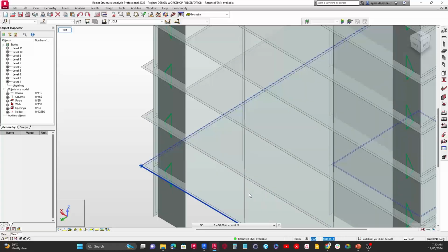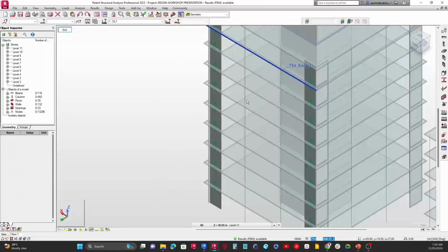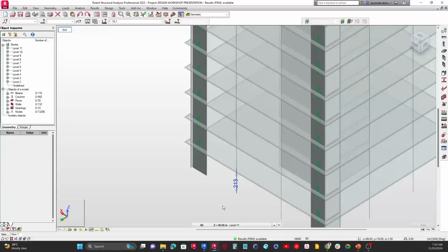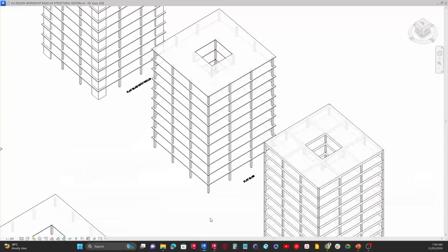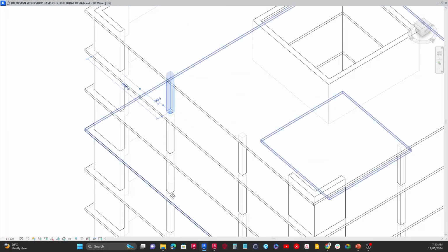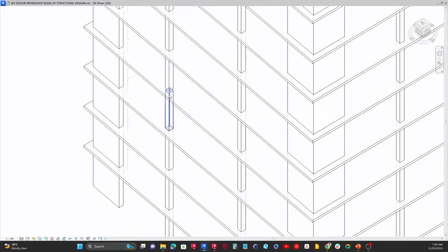All right, so the same thing applies to columns. The more loads that are coming from one floor to the other, it will lead to an increase in column section. So to practically demonstrate that, let me show you how it looks here. For instance, let's say this particular section works here, but if at some point it becomes so massive for the building, I can decide to change this column section to something that can support it better, right?